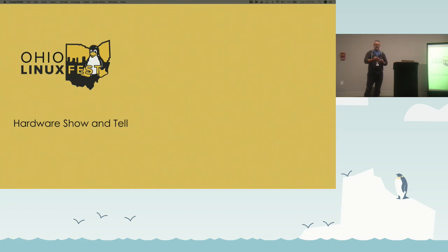And I like this because it helps kind of build an intuition. Like you plug this into a breadboard. Unfortunately, they designed it so if you plugged it into a breadboard, it covers up all the pins. So I need to build this wonky adapter to make it work. This is just a USB power supply, so it takes the place of a lot of the circuitry that would be on a finished board. But there's no USB to serial, there's no power supply, there's no GPIO pins. It's just the chip. So when you fiddle with this, you really get a good intuition of what the chip can do because you're only interfacing with the chip itself.